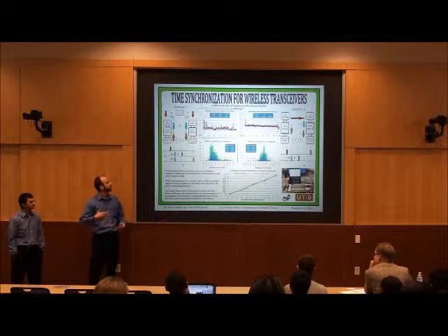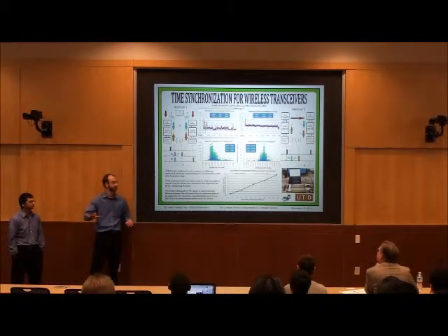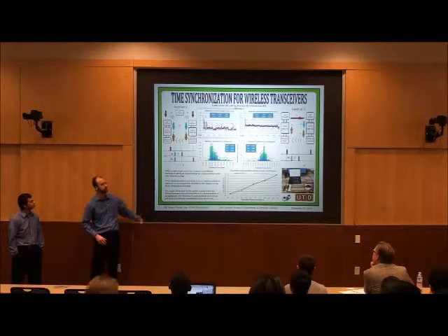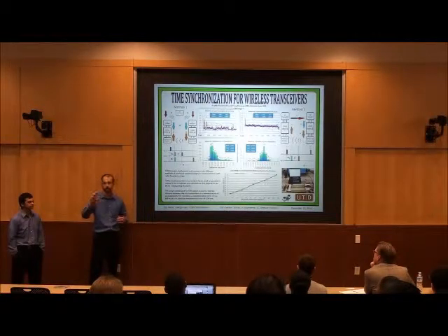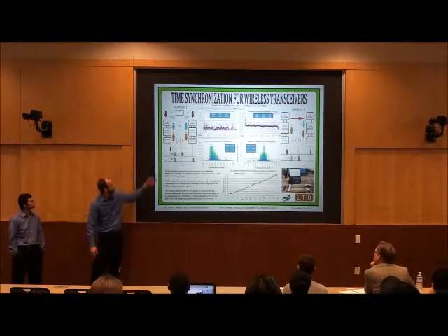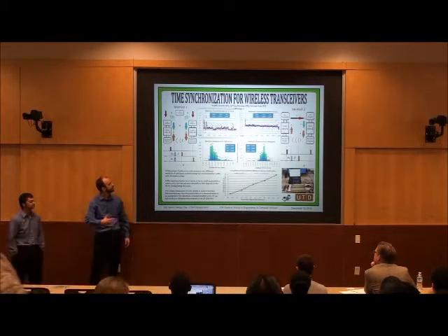Talking about our methods, method one here, focusing mainly on the synchronization and how that was done. Method one involves a separate RF transmitter, which transmits its own synchronizing beam to the microcontrollers, and then both of these microcontrollers have the same model of radio frequency receiver on it. So ideally, they'll receive the synchronization beam at the same time and be operating on the same time. You see there at T2, ideally they receive it at the same time.